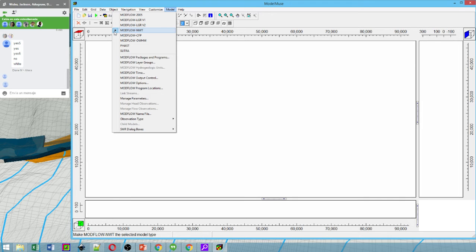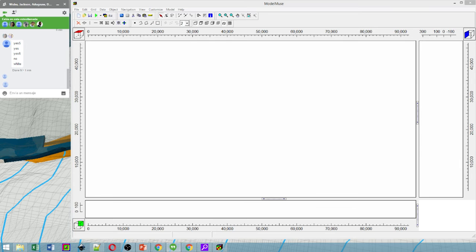That's a good question, Shuka. Because MODFLOW NWT is more adequate when you have a higher difference in the discretization, and this time we are going to model basins that have more than 1,500 meters between the lowest part and the highest part in elevation. That's why, from my experience, I recommend MODFLOW NWT. It deals better with high cells, dry cells and wet cells. Is that okay for you, Shuka? Cool, great.